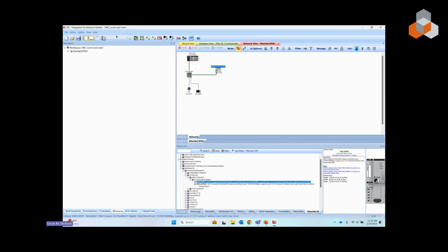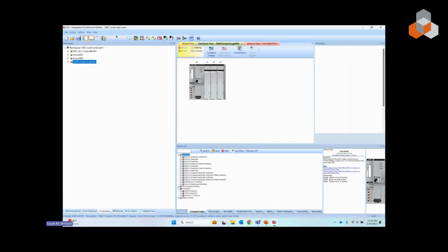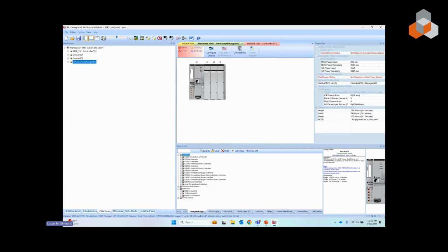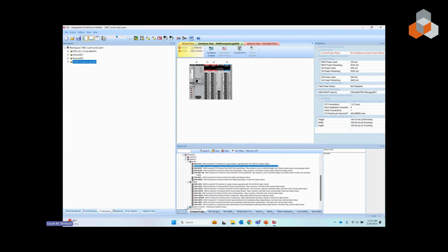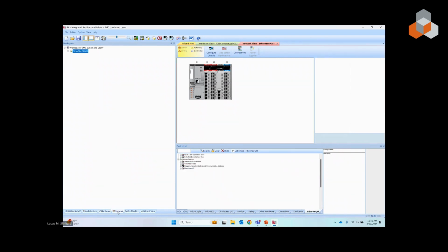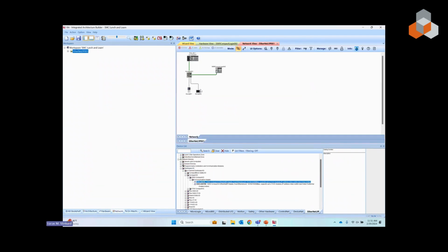Notice that we don't have any cards. If we wanted to add cards, we could go ahead and double click on there. We could start configuring this for the I/O that we need in addition. Maybe we need some additional IA16s. We would just simply click and drag, and maybe one more DC card. And once again, we see that FPD card as we go from AC to DC populated into our system. So now we have a pretty good control system going.